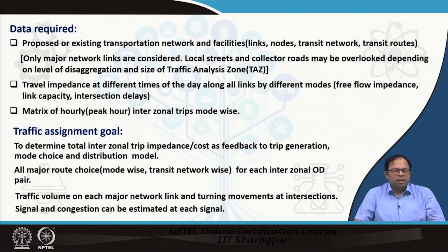But you can also understand this, that if you choose too many alternatives, then again the entire computational process becomes too time consuming. So we also limit the total number of options for route choice. Maybe we will look into 2 or 3 or maybe maximum 4 routes. If we go beyond that, then you can understand the amount of computation increases. You have to multiply that for each mode and all, and then the choices explode exponentially.